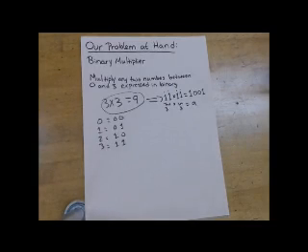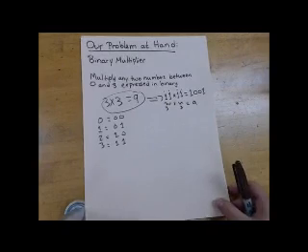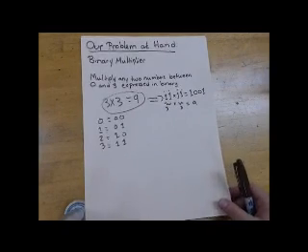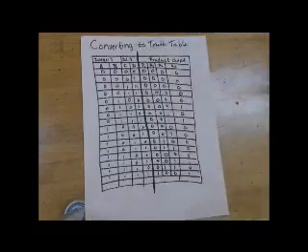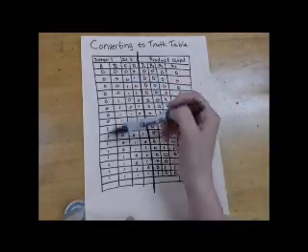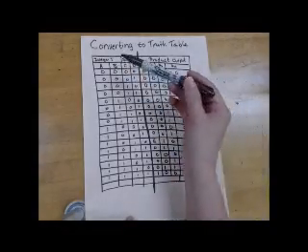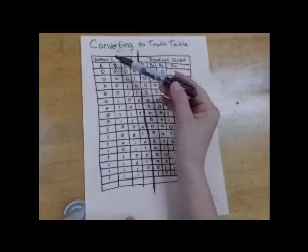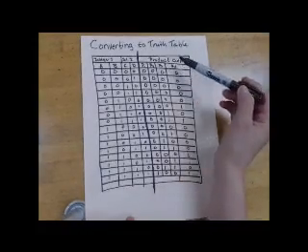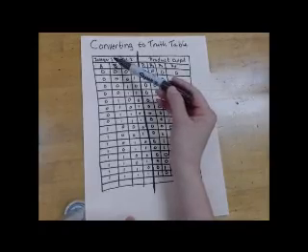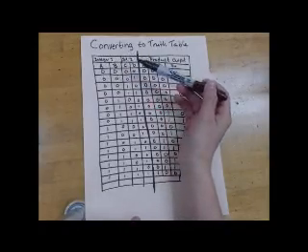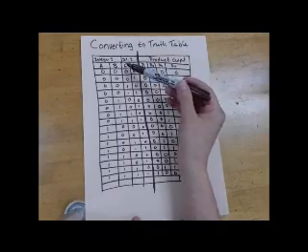So, how do we take this problem of binary multiplier and put it into what we've seen with logic gates and truth tables? Well, as it turns out, you can take this problem of binary multiplication and make one massive nasty truth table, and that's what this looks like. This shows all the possible combinations of the integers 1 and 2 multiplied together, giving the product output. So here you can see that integer 1 is made up of 2 bits, A and B. Integer 2 is made up of 2 bits, C and D.